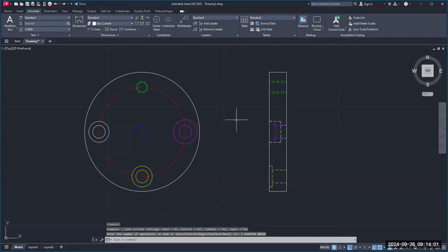All right, you type in the word chamfer. Or you can also select from the menu. Type in the word chamfer. Type in D as in dog. D, enter. And distance is 0.03, enter. Now watch. It wants to know my second distance is also 0.03, enter. So you had two distances you had to enter. They're both 0.03. It makes a foot.